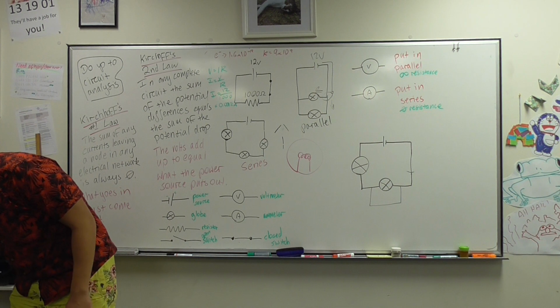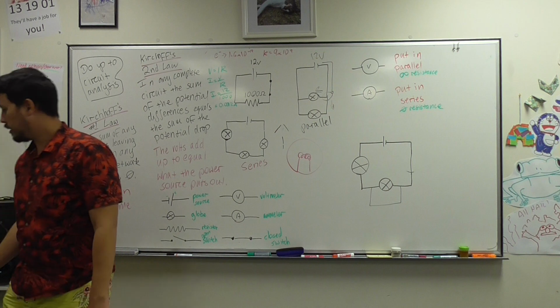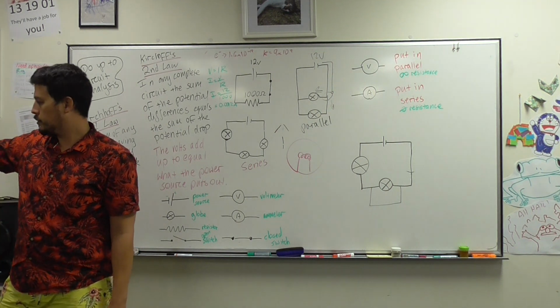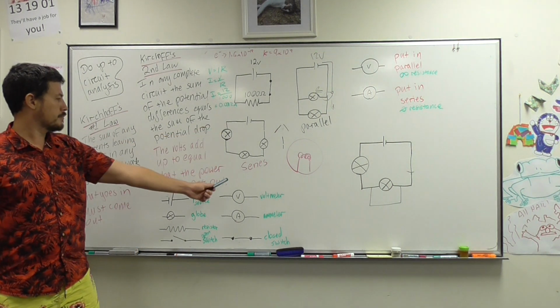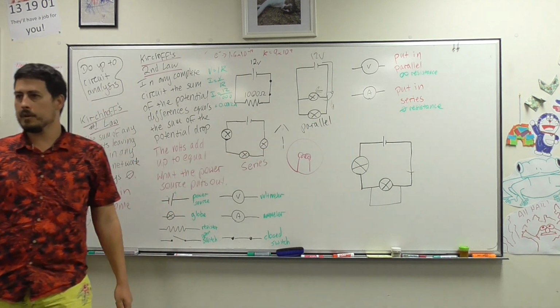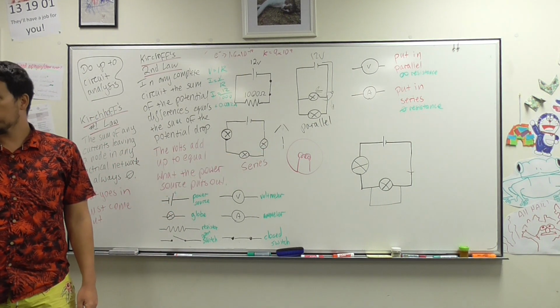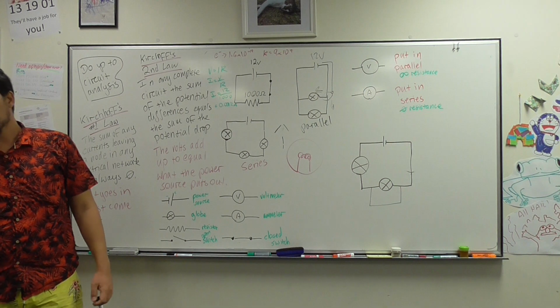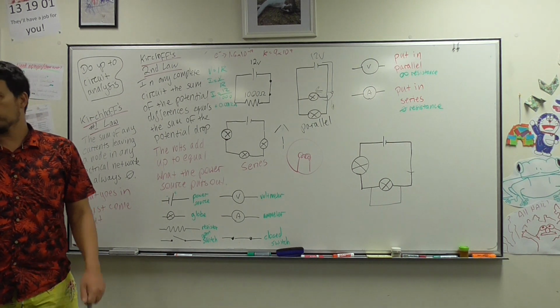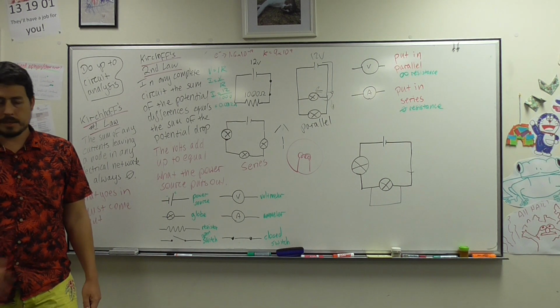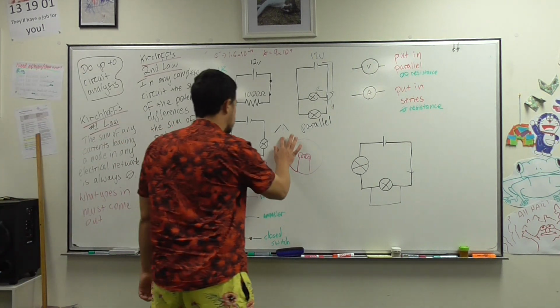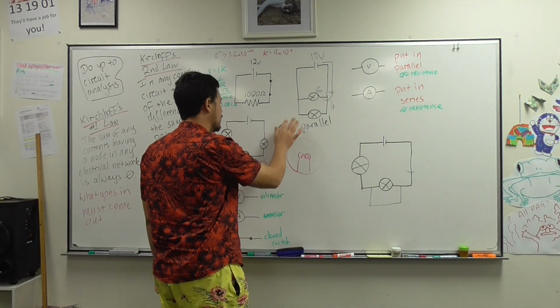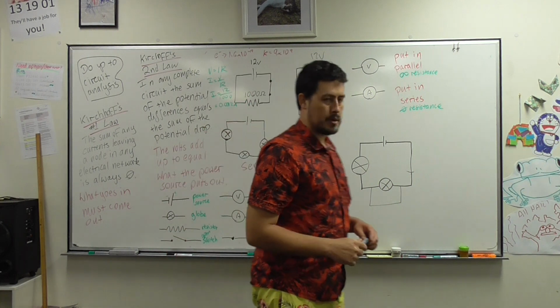And you'll get a nasty shock, even might die. But if the current is given an option to go down a wire through to the earthing prong, remembering that wires have very little resistance because they're copper, it's going to follow the path of least resistance. It's going to go into the earth and not go through your body, because it will choose the path of least resistance. So that's the first and most basic safety feature that exists on many items.